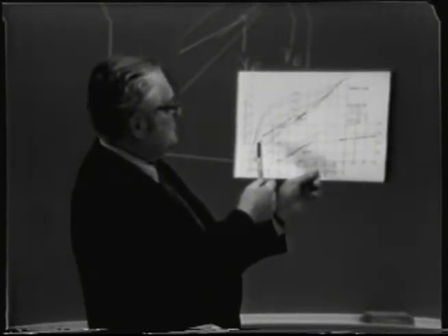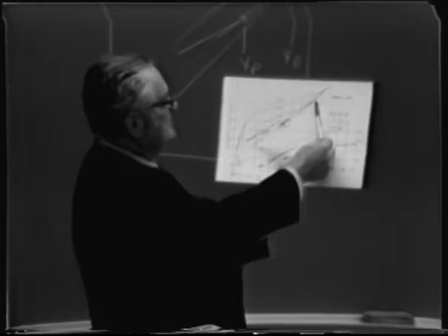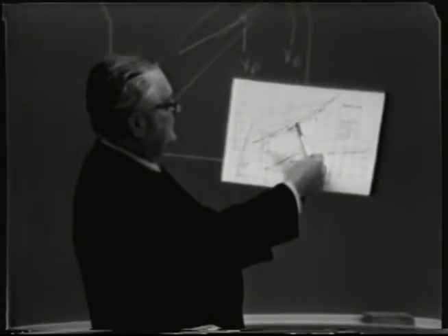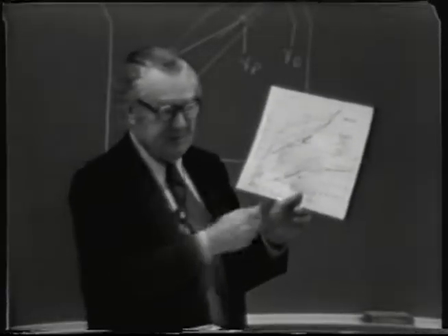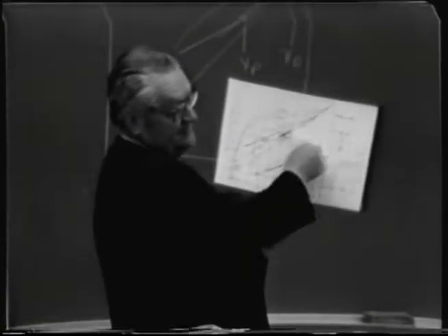Because the feed concentration is so low, there's no opportunity for this minimum reflux slope line to be established by the tangential point with the curve.